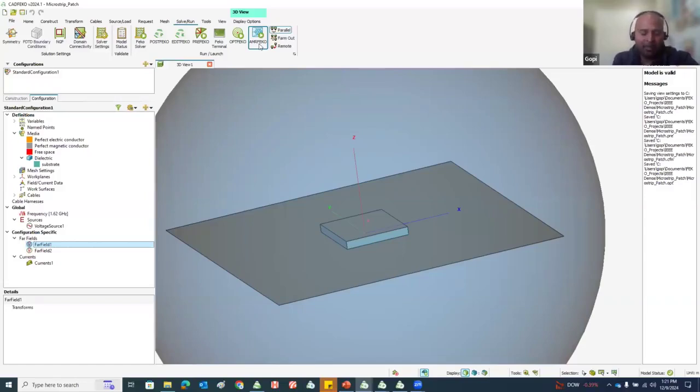So there, it assumes that the error is more. And in the other areas where the gradient is less, it assumes the variation is less and the results are accurate. And in the areas where the error is high, it will automatically add mesh refinements to refine the mesh and rerun the problem. So this iterative process will go on for a few iterations. And when the result is not changing with additional refinements, it thinks that, okay, this is the most accurate mesh because the result is not changing with any added refinements. It will stop and it will give you the answer. Okay?